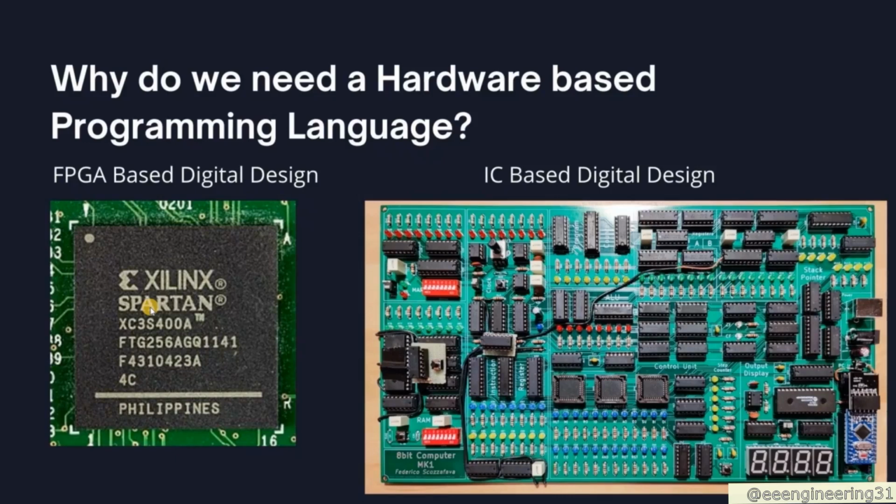Now, you might ask, well, can't I do this in any microcontroller? The answer is no, because in microcontrollers, you don't get to program the circuits, you don't get to program the timing of the circuits, you don't even get to program real parallel processing. FPGAs can work in parallel, so you could have multiple circuits all working totally in parallel. Now, microcontrollers, as we are going to see as we progress, execute in a sequential way, instruction by instruction. It's not parallel at all. At best, you could have multi-threading, which is a semi-parallel process.